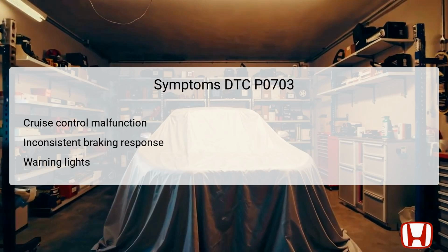When DTC P0703 is present, several symptoms may manifest, indicating that the brake pedal position switch is malfunctioning. One of the most common issues is a cruise control malfunction, as the vehicle may not disengage cruise control when the brake pedal is pressed.